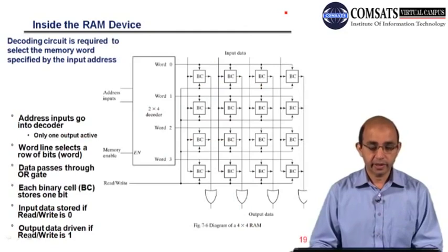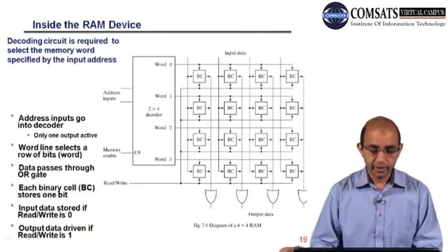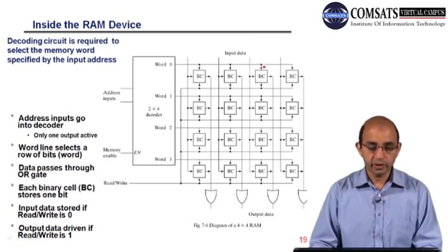So this is the inside story, right? You can see we have different binary cells over here, and those binary cells are bundled together in order to have a word, right? Here we have a decoder, and that decoder is being used for addressing those different locations.